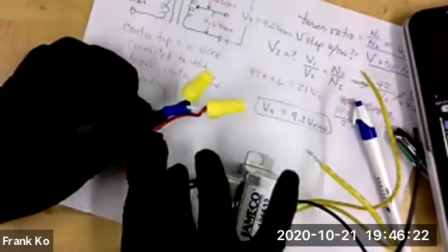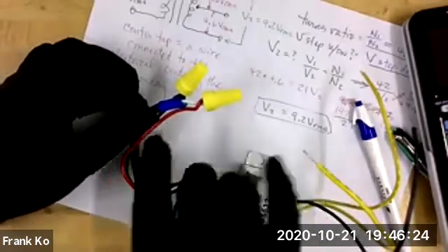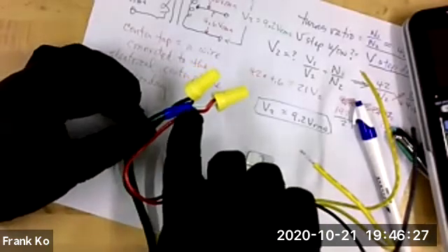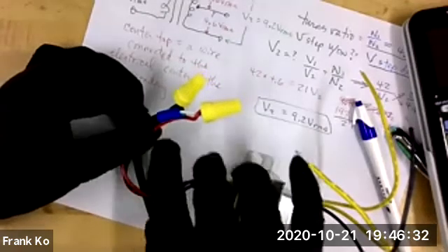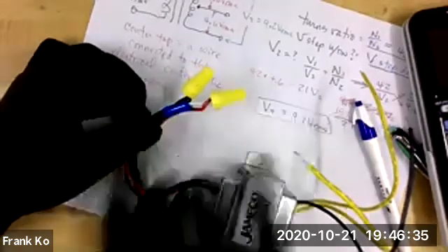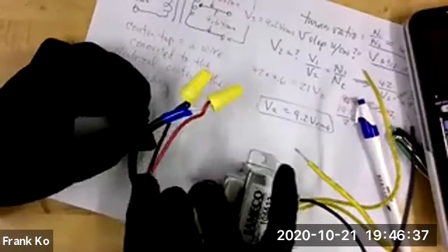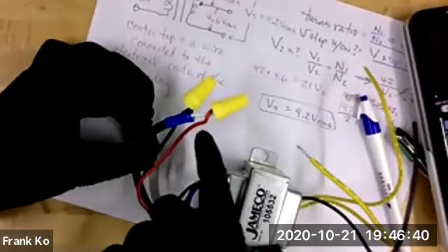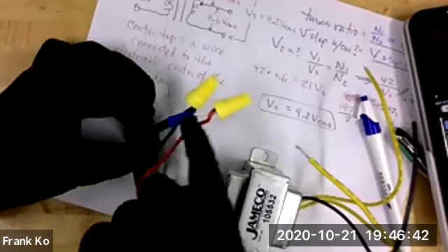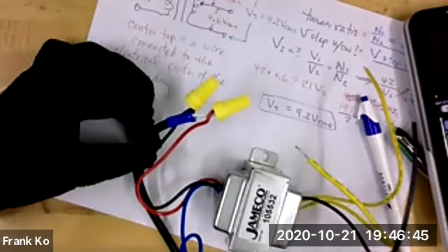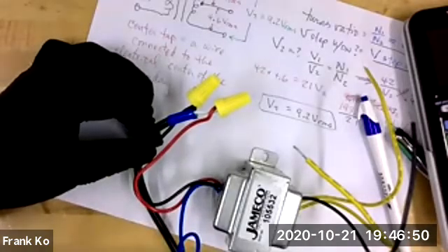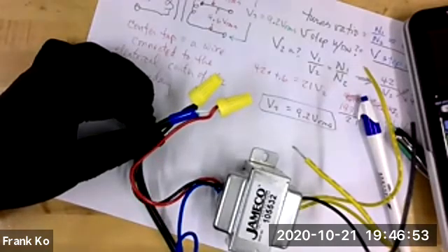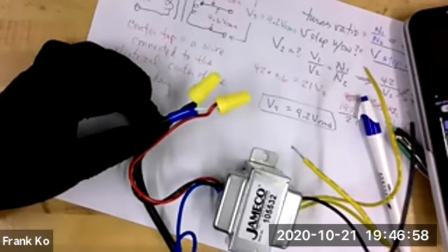Now with your remaining power cord wire, you can cut that short and fold it. Do not have any wire exposed. You could tape it against the body of the power cord. So my ground wire of the power cord, I've cut already and I've got it folded back. Fold it back and tape it to the body of your extension cord. So far, so good?